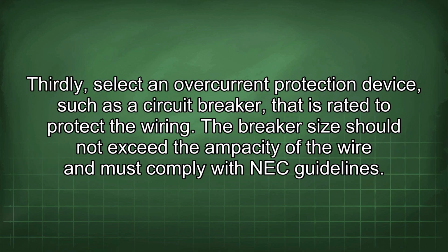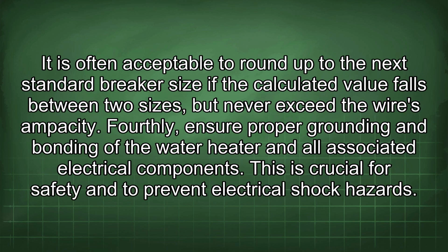Thirdly, select an overcurrent protection device such as a circuit breaker that is rated to protect the wiring. The breaker size should not exceed the ampacity of the wire and must comply with NEC guidelines. It is often acceptable to round up to the next standard breaker size if the calculated value falls between two sizes, but never exceed the wire's ampacity.